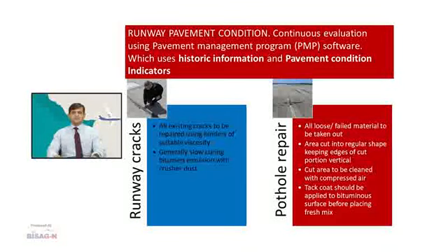While the procedures to repair runway cracks and potholes are well laid down, employment of pavement management program software, which assesses the history of the pavement and other pavement condition indicators to identify optimal rehabilitation points, is also recommended as a best practice. A consultancy service for formulation of the pavement management program may be utilized. As such, software parameters may vary from location to location and condition to condition.